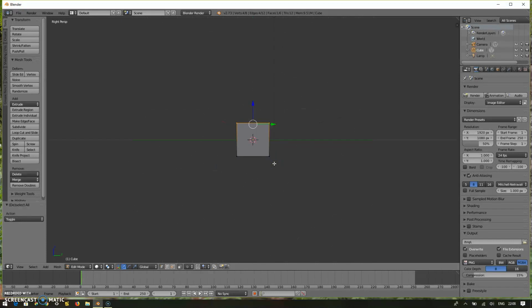To just see that, go to the front view and see that only the top portion is selected. Only that face is selected, rest of them are not selected. So whichever face you want, you can drag around, or whichever vertex you want, you can drag around to see that only the visible portion is selected. So if you disable this, what will happen? For example, now I deselect by pressing A, go back to the top view.